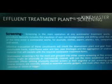The screening method is the main operation at any wastewater treatment works. This procedure basically includes the removal of large non-biodegradable and floating solids that often enter a wastewater works, for example, clothes, paper, plastics, tins, containers and wood. Effective removal of these constituents will shield the downstream plant and equipment from any possible harm, such as excessive wear and tear, pipe blockages and accumulation of undesirable material that will interfere with required wastewater treatment processes.